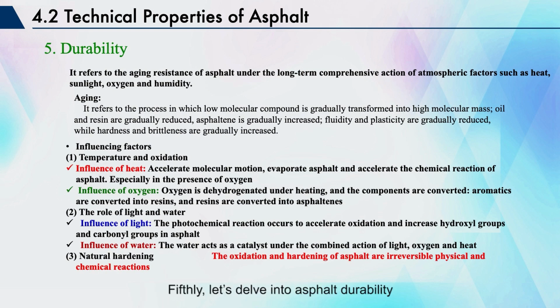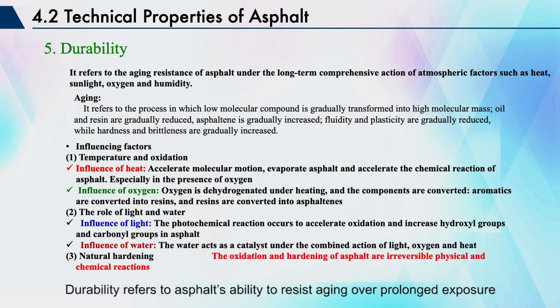Fifthly, let's dive into asphalt durability. Durability refers to asphalt's ability to resist aging over prolonged exposure to various atmospheric factors, such as heat, sunlight, oxygen, and humidity.